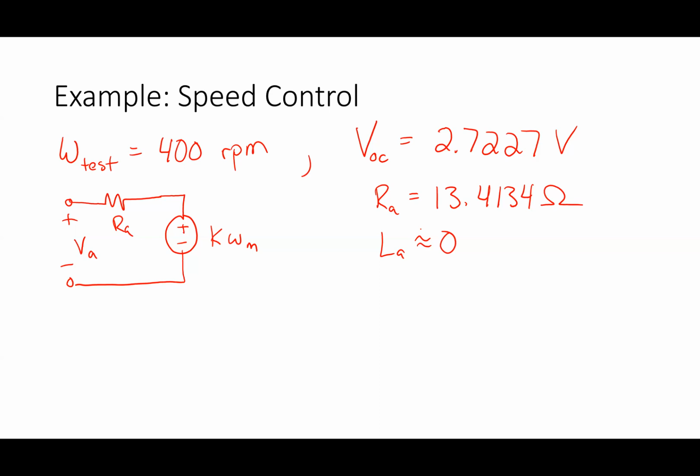If I'm going to output 100 MVA, I want that resistance to be super, super small, because I want all of the watts that are produced to leave the machine and not get burned up as heat. So one thing that's different here is that the resistance tends to matter, because these tend to be used in low budget applications, like your skateboard, as an example. We were talking about that yesterday. So the resistance is bigger than the inductance here, whereas with some of those other machines, the inductance is much more significant than the resistance.